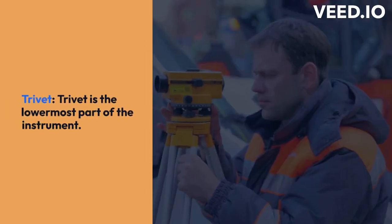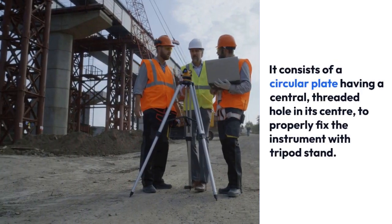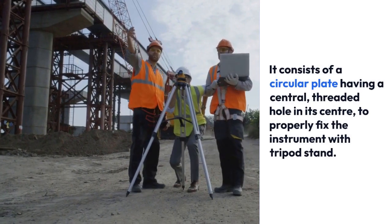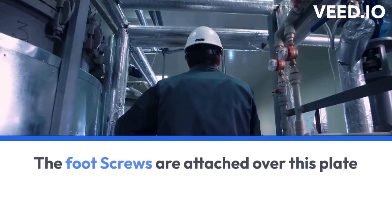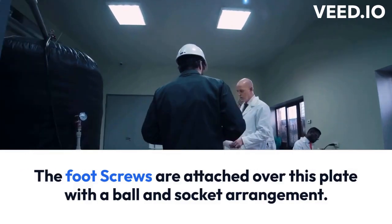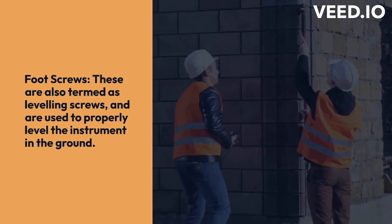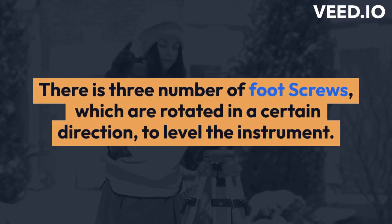Trivet. The trivet is the lowermost part of the instrument. It consists of a circular plate having a central threaded hole to properly fix the instrument with the tripod stand. This plate is also termed the base plate. The foot screws are attached over this plate with a ball and socket arrangement. Foot screws. These are also termed leveling screws and are used to properly level the instrument on the ground. There are 3 foot screws, which are rotated in a certain direction to level the instrument.